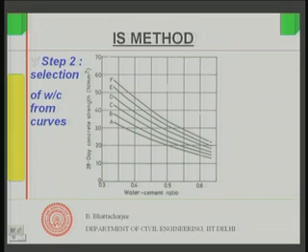Because if I did not know the cement strength, then of course I would have used one particular single curve which is there, and it will be very approximate. Oh well, it does not matter how approximate your mix design calculations are, because finally you have to do trial mix and you have to adjust. There is no other way. It is based on total empiricism, as I said. So there is no other way you can get rid of trial mixes. You have to do a trial mix, and this is only the starting point you are getting.